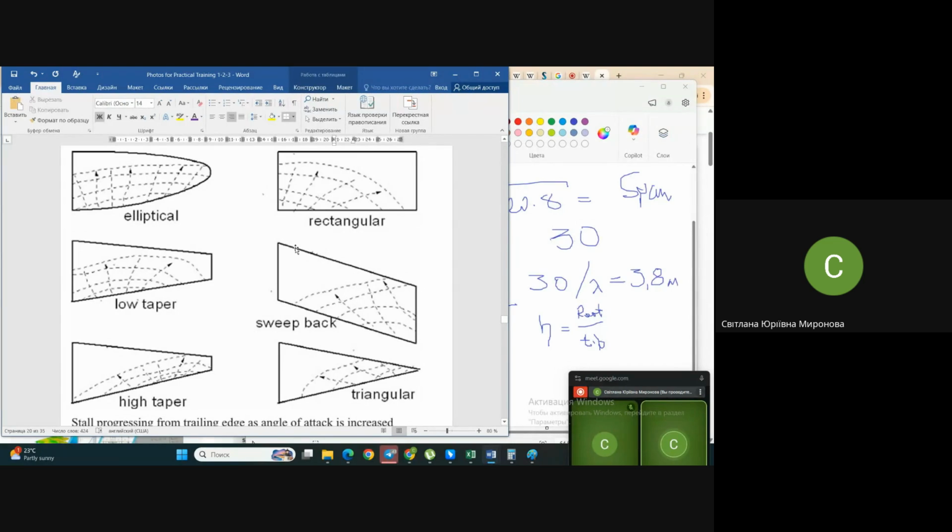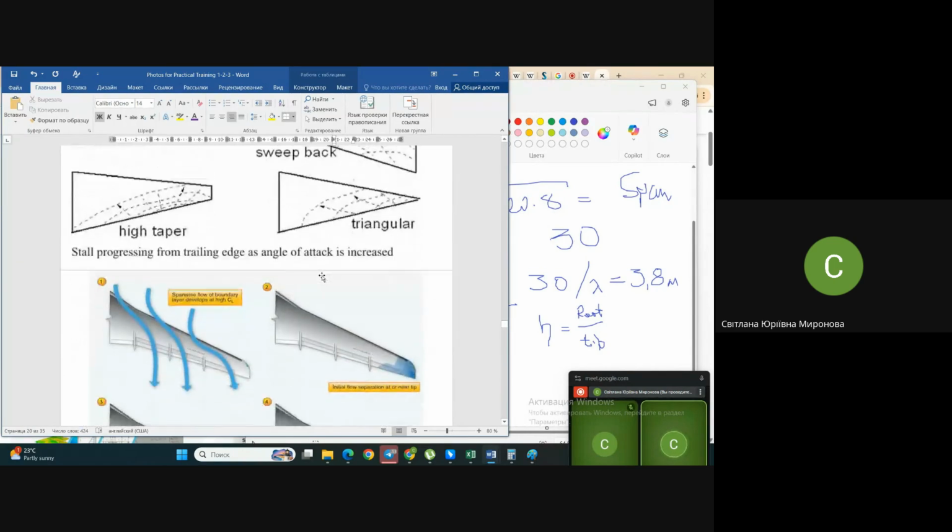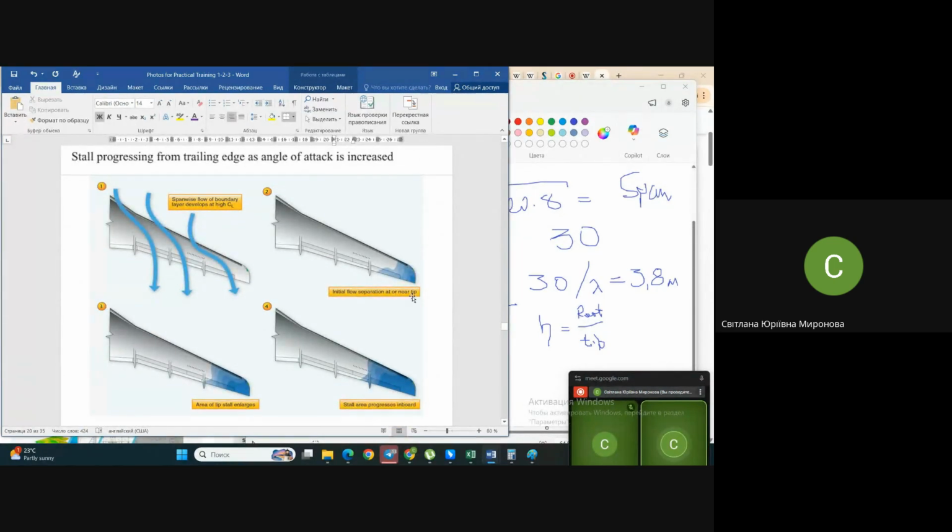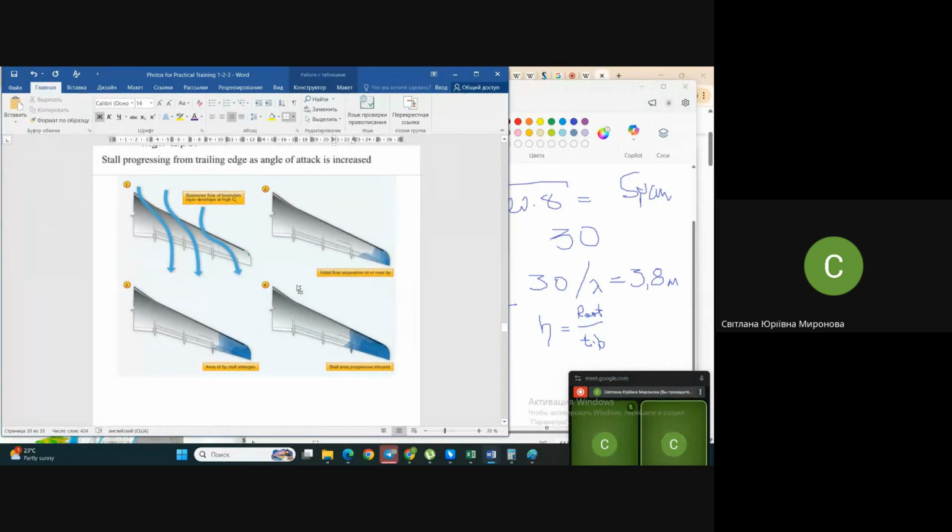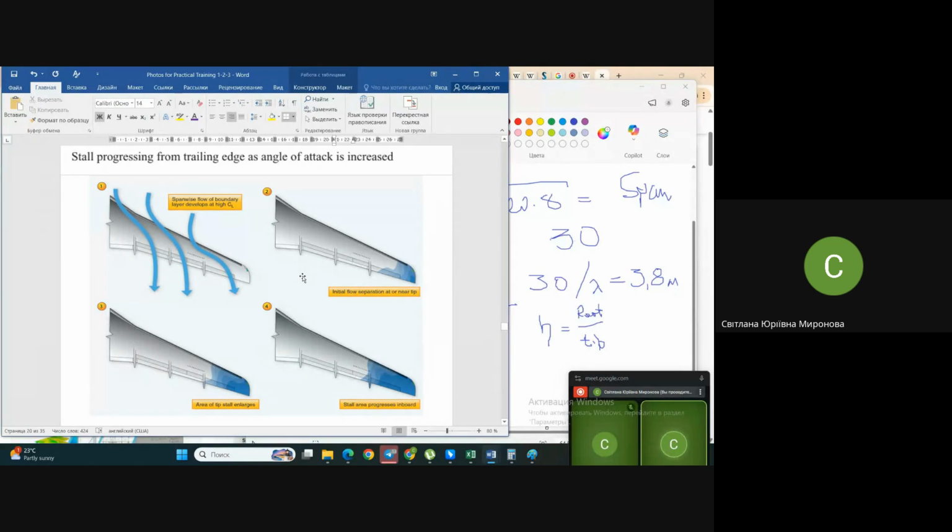And moreover, I hope you remember such things as winglets, deviated wing tips, that have now become practically a standard of passenger aviation, as I already said. These winglets may help you to partially solve the problem of the swept wing's wrong downwashing at high angles of attack. So the swept wing, in this meaning, is more preferable with respect to the straight wing, in case you have to decide which one.